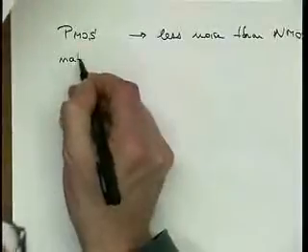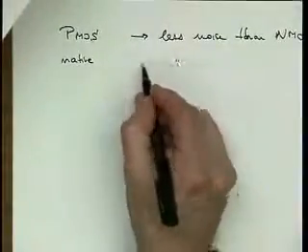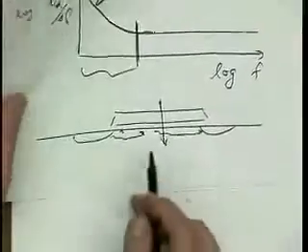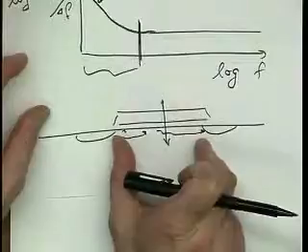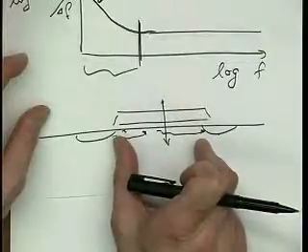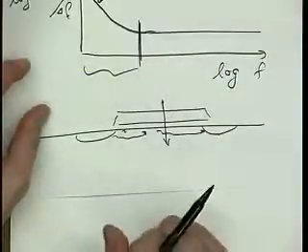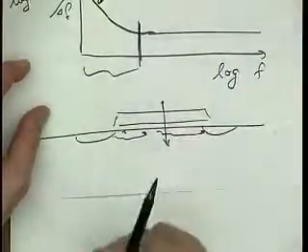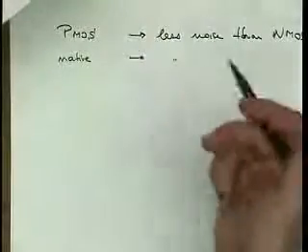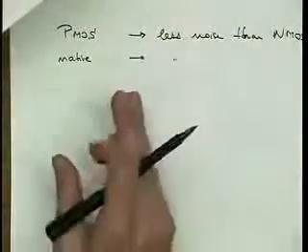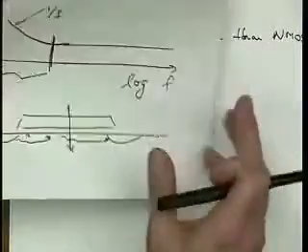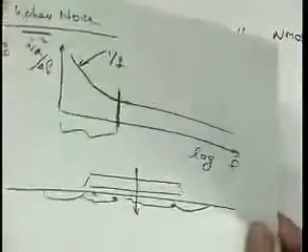Native has even less noise, typically. What is a native device? Well, it's a device that has not received any threshold voltage adjustment. So an N-channel device usually will have about 0 volt threshold voltage, and increasingly those are available in modern technologies. They have a mask to do that. Probably not for this reason, but we can use it. So sometimes if we need really little flicker noise, then the native device may be attractive. Okay.